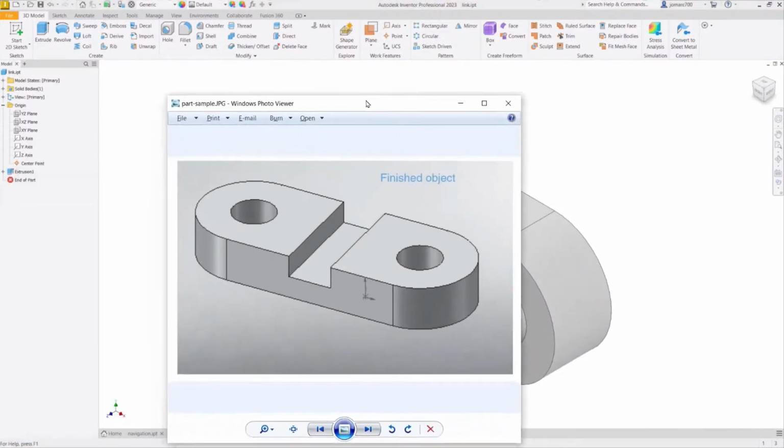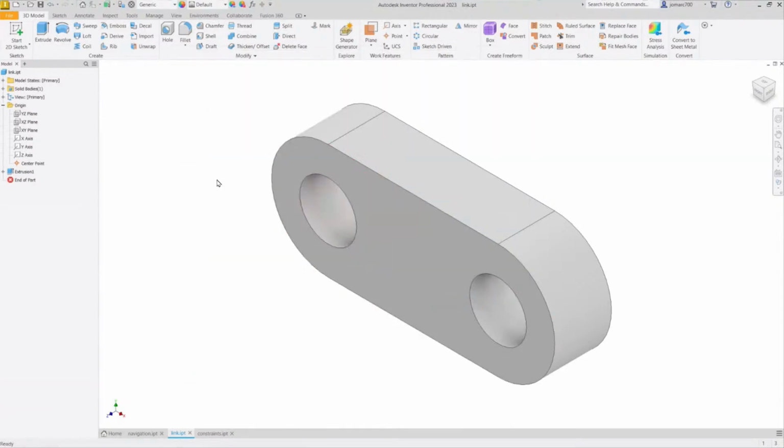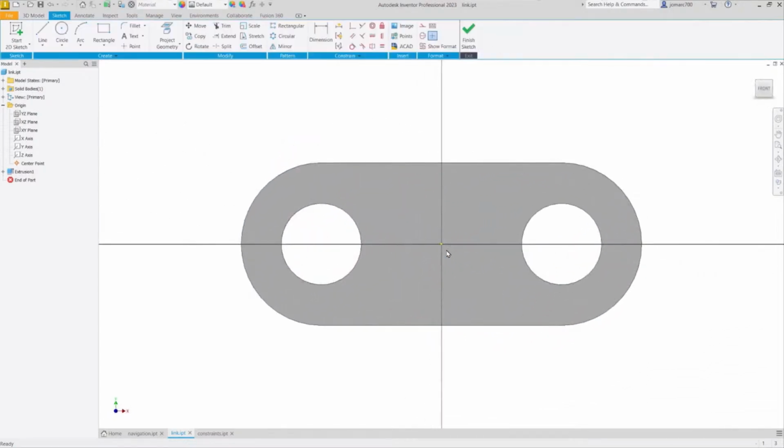And to create the cut extrusion on this location, it's simply repeating the steps we have made before. And this time, instead of creating a sketch on a plane, I'm going to select this face. So notice these icons appear. And from here, I'm going to select the one on the most right, which is create sketch.